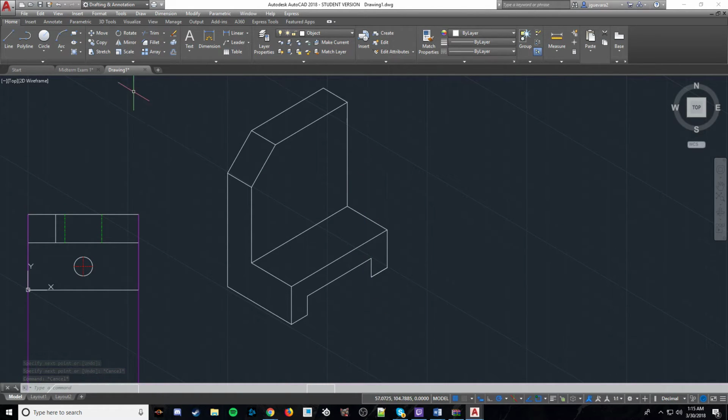We're also missing now an important part: the circle that needs to lie flat. So we're going to type in ellipse, because that's what an isometric circle is. Hit enter. Don't type any values in yet. You're going to notice ISO circle right down here. Type in I, hit enter. It's going to give us an ISO circle. Flip your view to where you want it.